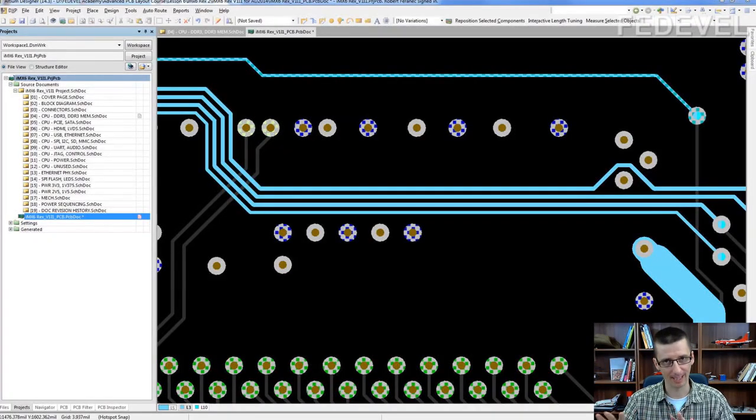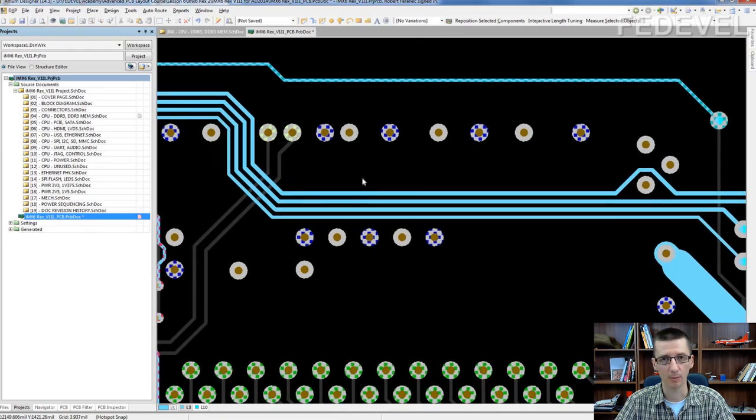I said everything important I wanted to say about the memory interface, and now we can move to a different topic. When you finish preliminary length matching, then do something I call spreading the tracks in your design.